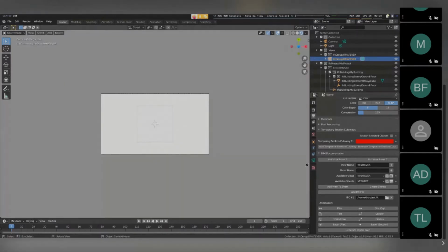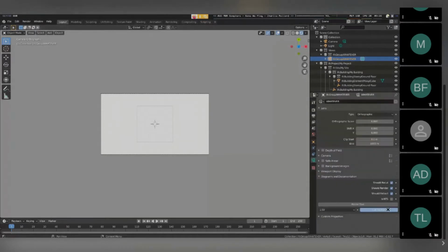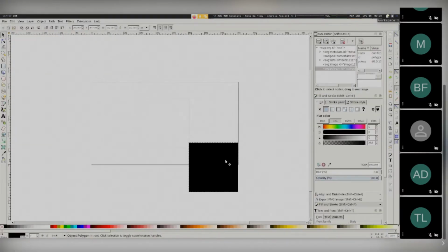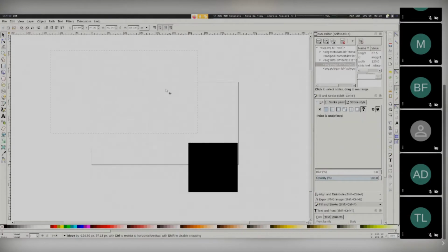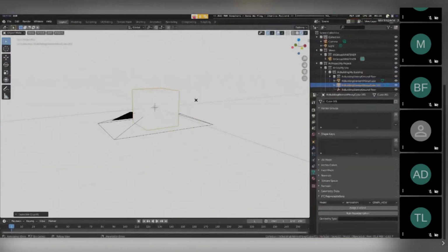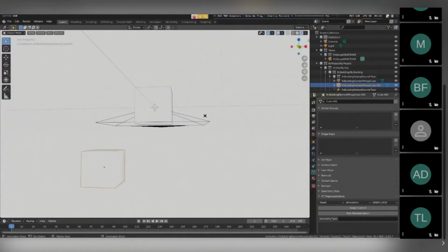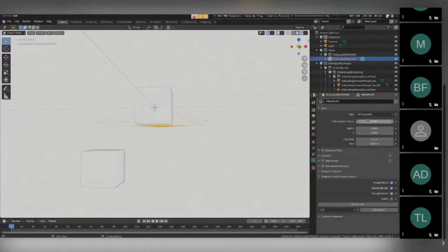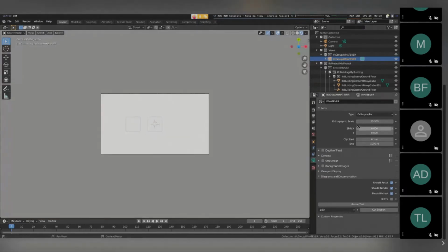So if I've changed it to the construction style one, and if I, again, active camera cut section, you can see there's my rasterized background. So if I now have 2 cubes, and one will be cut by the camera, one will not be cut by the camera. Let's increase the size of that so I can see both of them in my image.